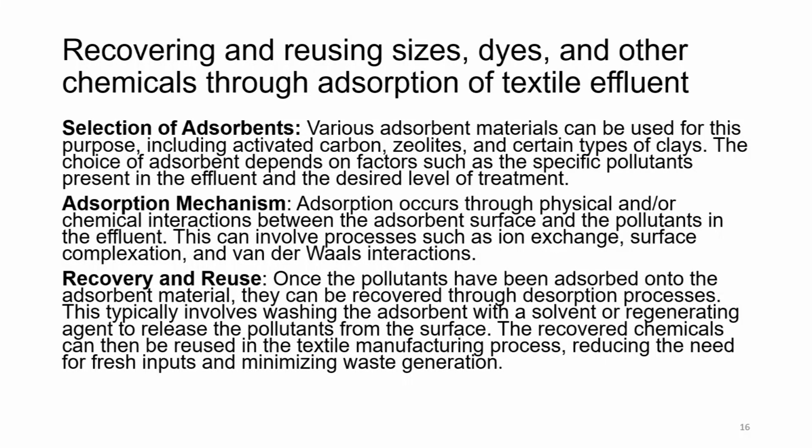Adsorption mechanism we have studied in the past, but we will re-look at in terms of recovery and reuse phenomena. Adsorption occurs through physical and or chemical interaction between the adsorbent surface and the pollutants in the effluent. This can involve processes such as ion exchange, surface complexation and van der Waals interactions.